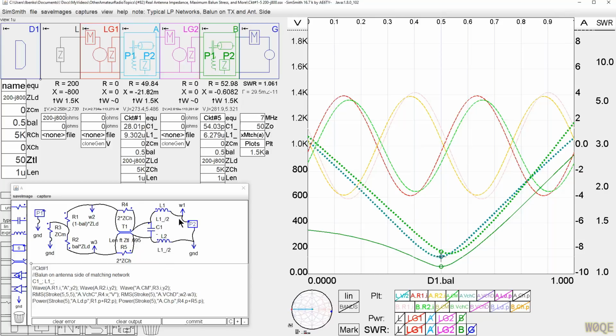Putting a symmetrical matching network here and a much smaller balun is one way to go. The other way is brute force: an unbalanced tuner, and just make this balun much larger than it would otherwise need to be. Then you can handle the incredibly high impedances that you will potentially get with a loop or a dipole and open wire feed line at certain frequencies.